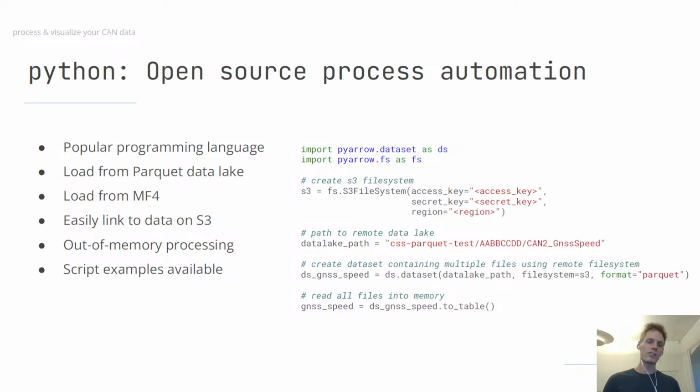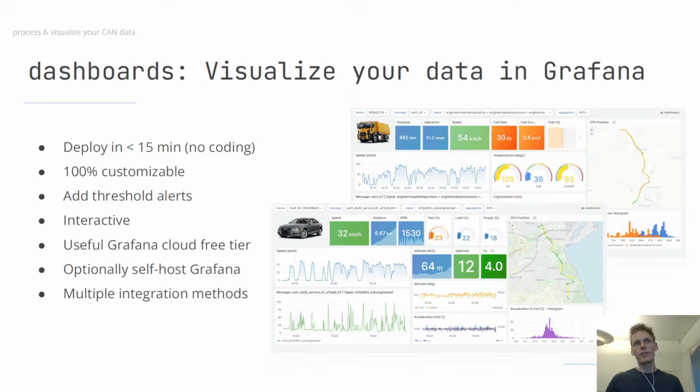But if you want to process data at scale with Python from the CANedge or from many CANedge units in a seamless way, where you can ignore whether it is from log file A or B or what time period it is from, then this is the way to do it. And for both MATLAB and Python, we provide some basic script examples to get you started in the new MF4 decoder documentation.